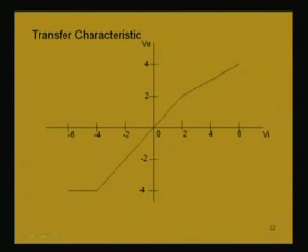When it is greater than 2 volt, from this point to the peak point when Vi is 6, the voltage at the output is 4. So, these 2 points you can just connect. To get a straight line, only two points are needed, minimum 2 points. So, we connect these two. This will be the slope for this portion, that is, when input voltage is greater than 2 volt. In the negative half cycle, again up to minus 4 volt, input and output voltage are the same, because